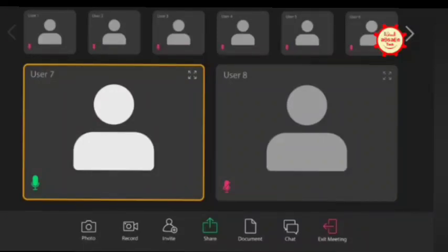maximum users use Division 1 only, and Division 2 and Division 3 are normally used when the weight of the material needs to be reduced. In that case they go for Division 2 and Division 3. Their intention is to use Division 2 and Division 3 more. But I didn't hear about the merging of Division 1 and 2.